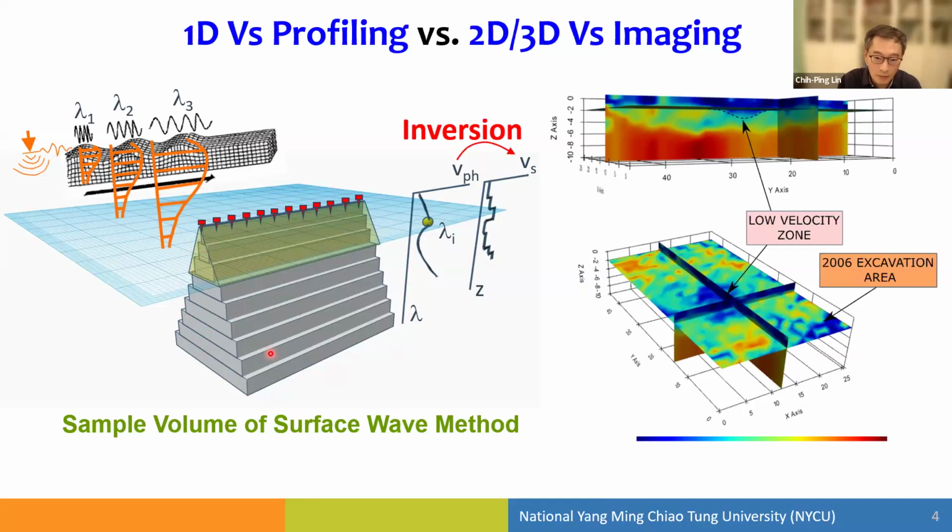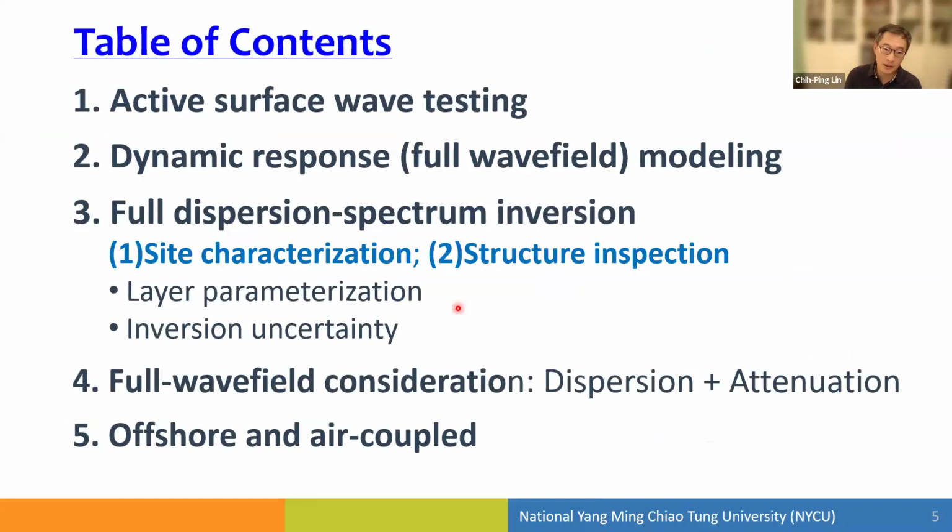And also from this exercise, you can come up with a very good estimate of the 1D shear wave velocity profile, which, if you are interested in conducting 2D full waveform inversion, could be a much better starting point. And so I just want to make clear what kind of problem we are dealing with, right, before I really start my presentation.